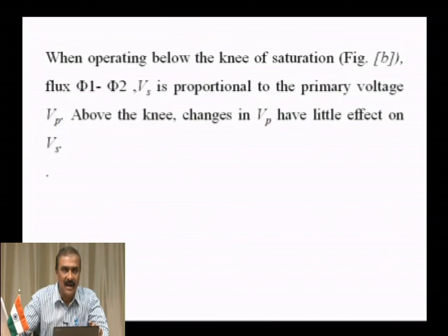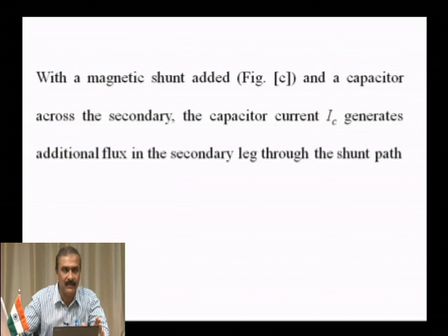So, another important thing is that they have little effect on Vs, that is secondary voltage. Above the knee, changes in primary voltage have little effect on secondary voltage. Even if you increase Vp, Vs will not increase. This is the regulation requirement.